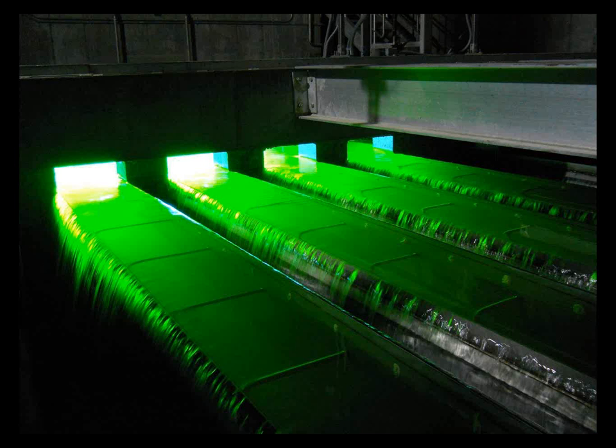Because of a batch discharge, you can't get bulbs lit in time, and if we didn't have this system, we might discharge water that hadn't been disinfected. So in order that doesn't happen, our bulbs stay on all the time, as some of them do, so that the minute water flow hits it, the bulbs are already on, already disinfecting instantaneously, and then more bulbs will light as the flow increases.